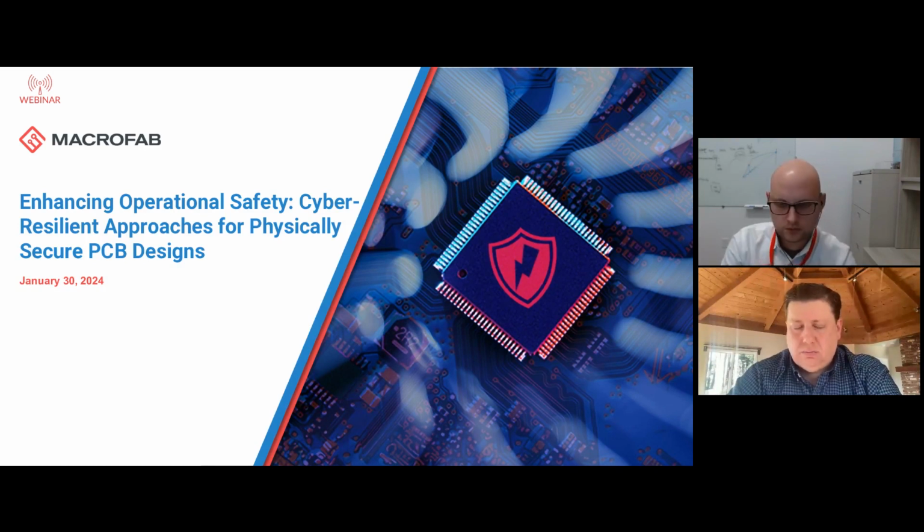Yeah, we touched on a couple of those. But again, the main ones are the accidental mistakes that happen when you don't enforce the procedures you put out in an automated way. It's very easy for people to make mistakes at final hardware QA stages or with non-automated tests, to forget to turn off the debug output, or it's up to an engineer at compile time to make sure they add the flag that says turn off debug or turn on optimization, which is another good way to add security through obscurity. If you're manually doing those things, it's easy to make those mistakes. So a lot of this is, once you make a decision on a security approach that you want to take, try and enforce that through automation, and then double check yourself through testing.